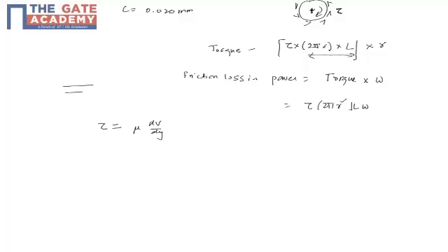This is like between two plates, but now you are applying it between the shaft and the bearing. So mu dv by dy, in the thin gap, assuming a linear variation of the velocity of the fluid in that clearance. So this is v, this is 0, and this is your clearance c. So it is mu v by c, and v is the surface speed of the shaft, which is r omega, so mu r omega by c.